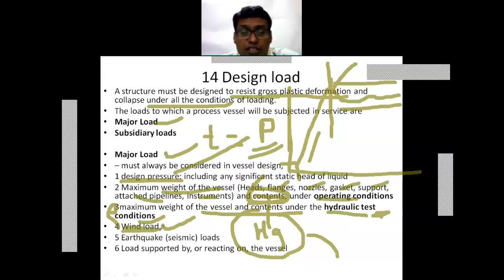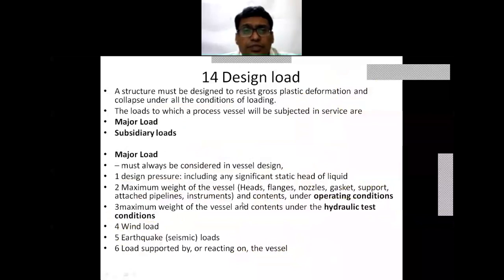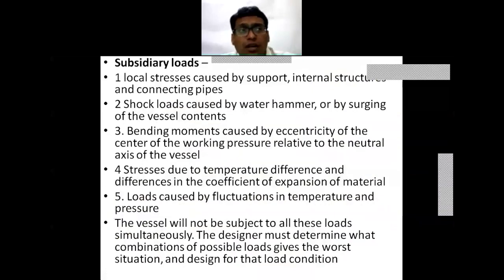But for tall vessels and areas where high wind loads are there, one has to take this wind load design parameter seriously. Then the earthquake, that is your seismic load, which is to be considered depending on the earthquake-prone area. Then the load supported by reacting on the vessels. So these, and the subsidiary loads, are our important loads.